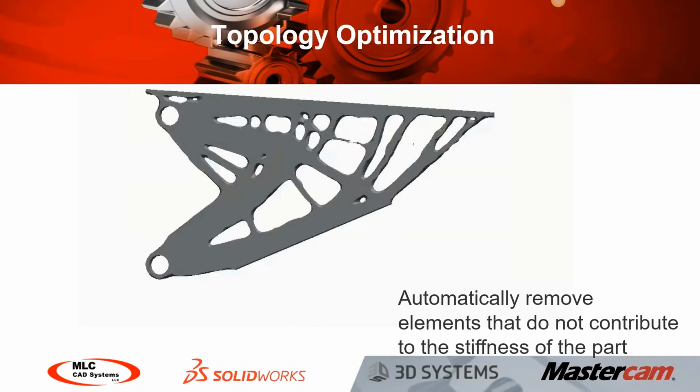In a topology study, we don't have to have features or dimensions defined for the shape to be adjusted, meaning you don't have to know what the final design should look like before you start the study. We can start with just a simple model of our maximum design space, which is what I'm going to show you in a minute, and define our features and loads, and then let topology show us what the optimum design should look like.